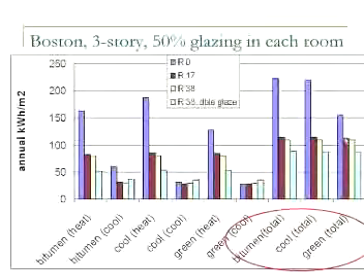More recently, we've done a study looking at U.S. building stock, and what it says is if we're talking about old homes, 1950 to 1970, where the insulation level is fairly low in the attics of the homes, in many cases, adding insulation will have a greater effect on energy efficiency. And in fact, if we look at global warming, we'll have a greater effect on global warming, because as we reduce the energy consumption, we reduce the amount of CO2 that's going to be generated over the lifetime of those buildings.